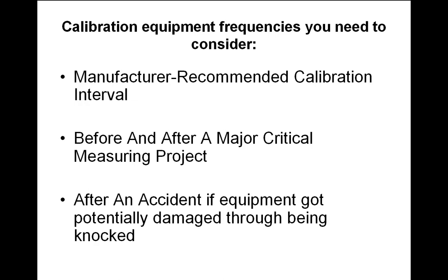Okay, calibration, we're talking really about measurement instruments, but just to put your mind back, when we were looking at the 24-volt power supplies in the PMC, they had a tiny hole, and you could put in a tiny screwdriver, and there would have been a tiny screw connected to a potentiometer, and you could calibrate there as well, so you could get the voltage up and down.